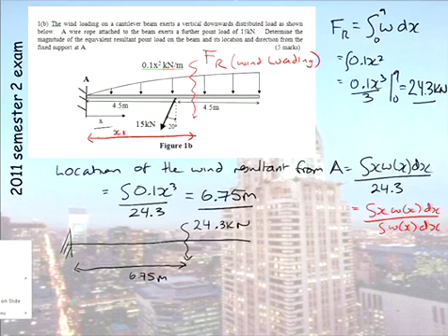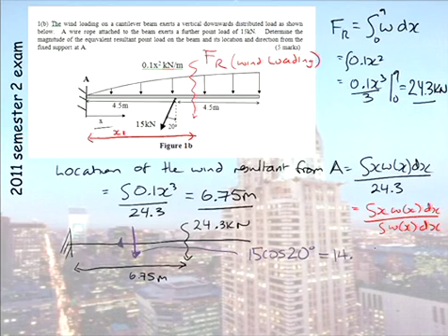And then in a different colour, I would resolve this 15 into a horizontal and a vertical component. So this vertical component here is simply 15 cos 20 degrees, because you're told it's acting at an angle of 20 degrees with the vertical. And this horizontal component, hopefully it won't be a surprise to find out it is 15 sine 20. So a value of 5.13 kilonewton.